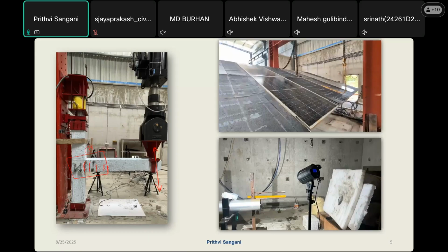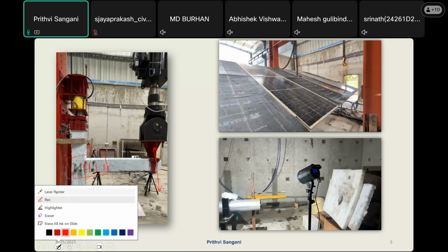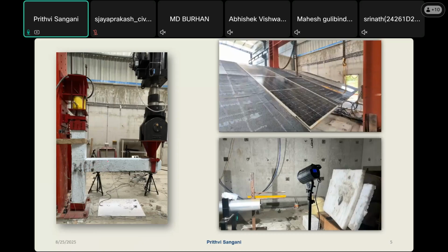Fine. So my question is, can you see such cracks in STAAD Pro? We can't see those cracks, right? In STAAD Pro, it only gives you what your reaction forces, bending moments, and displacements are, and stuff like that. So if you want to see where the cracks are coming, that's where you use this finite element tool called Abaqus, where you try to understand how the crack is propagating, and why we want to know why the crack is propagating. That we'll study in the further slides.